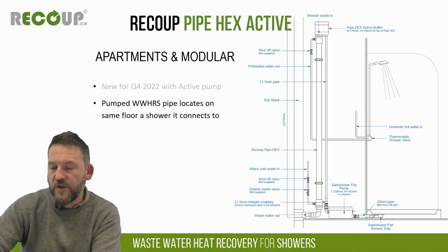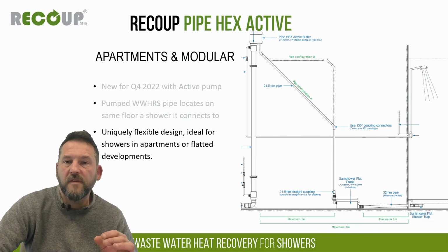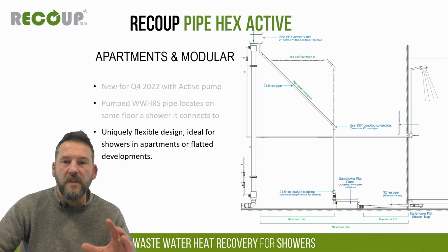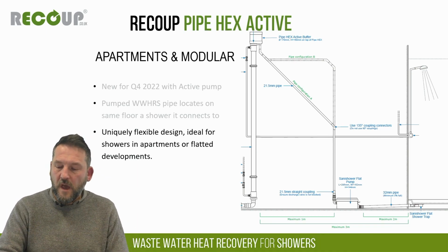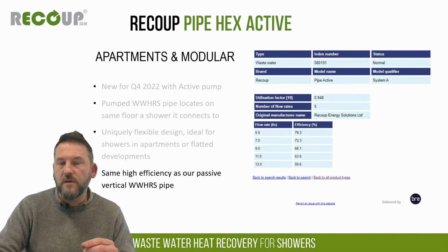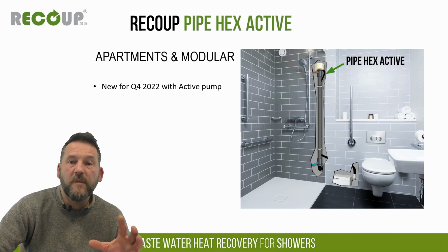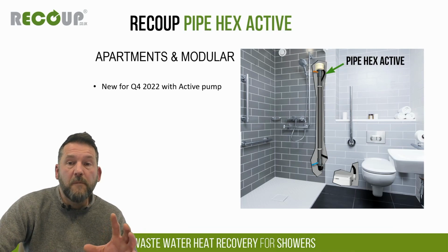But obviously we are introducing here a mechanical pump system. It does have a lot of flexibility in design, so it means that in bathrooms and podded systems, it can be designed in quite flexibly. But as I've alluded to, we are introducing a mechanical component here, so the pump unit itself does need to be accessible.